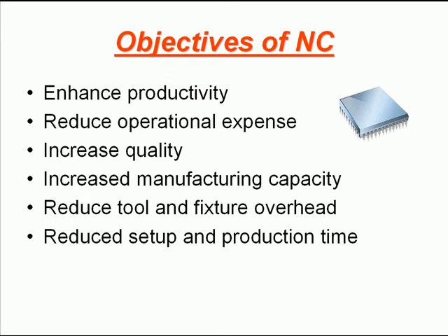Increase manufacturing capacity. If you have a punch press, I'm sure a lot of you have seen a punch press in a manufacturing plant. You have a die that comes apart, and generally the material goes in the middle. Then the punch press comes down with very high pressure, and it makes a part. But some of those dies are thousands and thousands of dollars, and they can make parts a lot faster. But anytime you want to add a hole or make some changes, it's not that flexible.